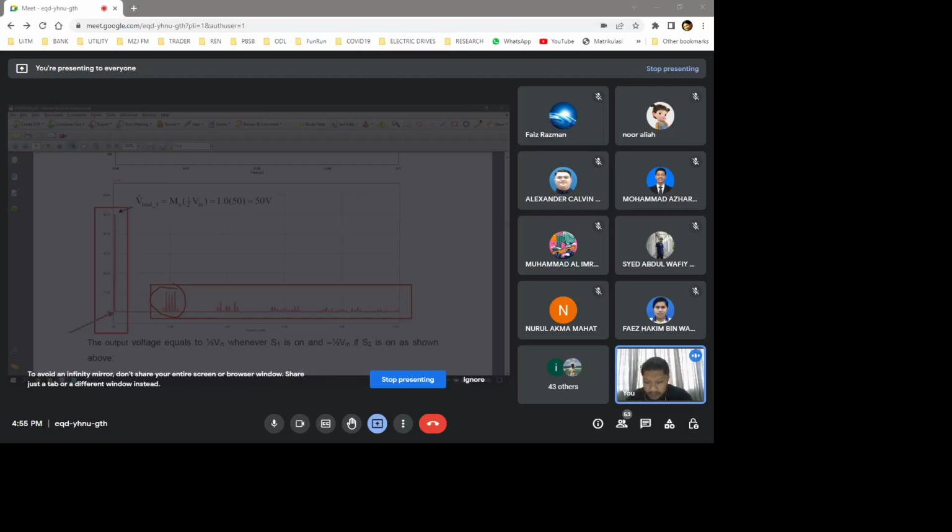The fundamental depends on the main frequency. So this is 50 hertz. At 50 hertz, this is the fundamental component, V load with a hat, and this is the harmonics. Okay, so again, if we can remove these harmonics by using a filter, what is left is only the 50 Hz component, just like the square wave and quasi square wave just now.